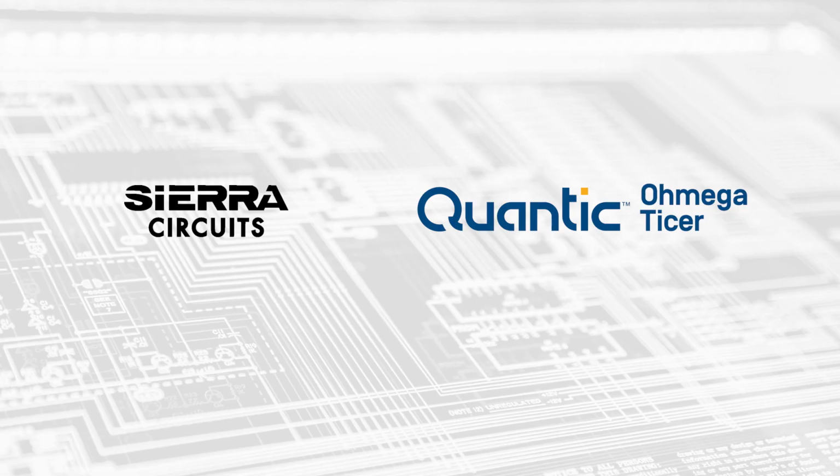And the last one is if they need an 8-layer board for a design to incorporate embedded passives, well, I need 10. Okay, so the thing with resistors is the answer should be no, because you're basically putting the resistors, which essentially would have been on the top anyway, down inside. So you're not really adding an extra signal layer. You're just getting rid of the via and putting the resistor where it normally would be. In the circuitry, it would be exactly in the same place, so there's no additional layer you would have to put.